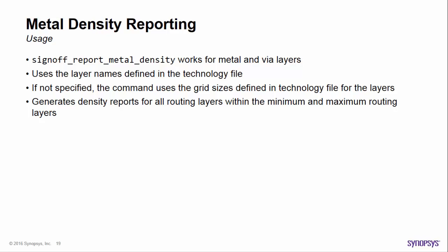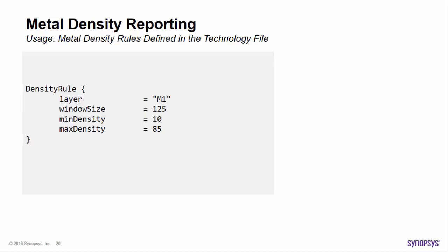It generates density reports for all routing layers within the minimum and maximum routing layers. Usage. This slide shows how the density rules are defined in the tech file.